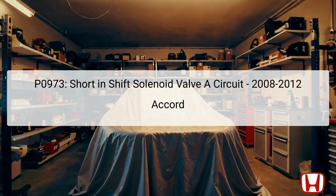The DTC P0973, which stands for Diagnostic Trouble Code for a short in shift solenoid valve A circuit, specifically applies to Honda Accord models from years 2008 to 2012. This error indicates there's an electrical circuit issue, which is separate from any mechanical issues that could happen within the transmission system. The shift solenoid is a key component as it controls the flow of transmission fluid and aids in